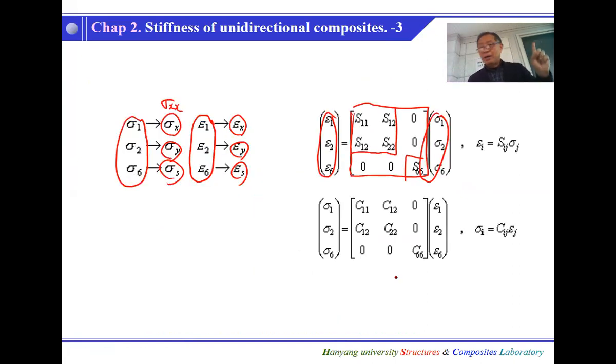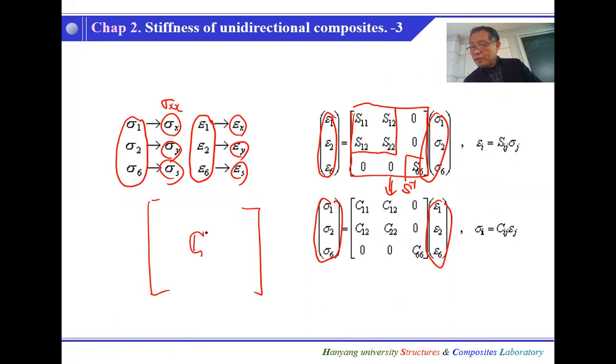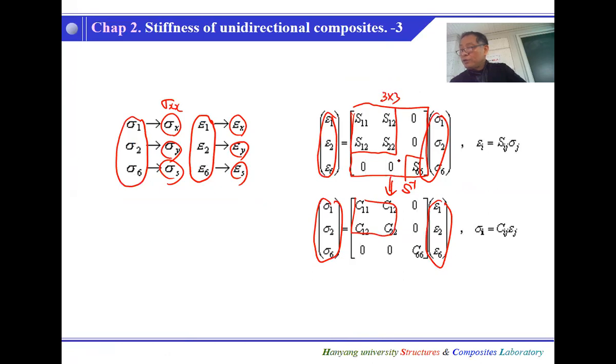Now, how about the stress in terms of strain? We have to invert this S matrix. Please don't take the values from the 6 by 6 C matrix; those are wrong. These values need to come from this 3 by 3, and you simply invert.